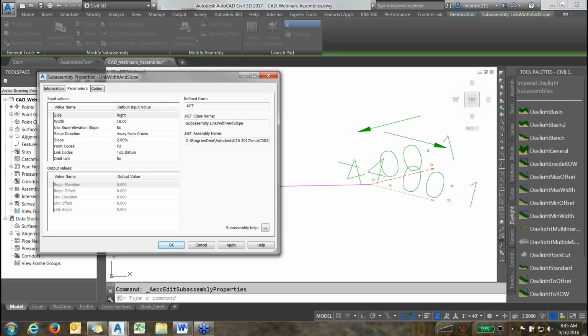So if you go down there to where it says the first subassembly parameters, the width is always, if you're doing parabolic, again, this is for a parabolic waterway, I'll talk about a trapezoidal one once I'm done. But for parabolic, this first line width is always a quarter of the waterway width. So since I'm doing a 40-foot waterway, I want to take a quarter of that. That's 10 feet. Okay, and this subassembly is already defaulted to 10 foot, so that's okay.